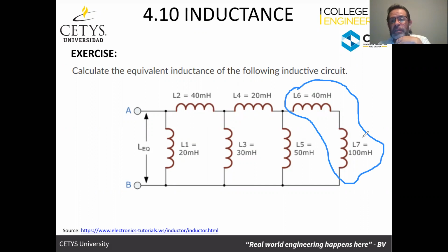The 2 inductors that I marked in blue, are they connected in series or in parallel? You're right, they're connected in series. How do I know? If I try to identify the current going through these, going from L6 to L7 or L7 to L6, there's no interruption or separation of the current. That's why they're in series.